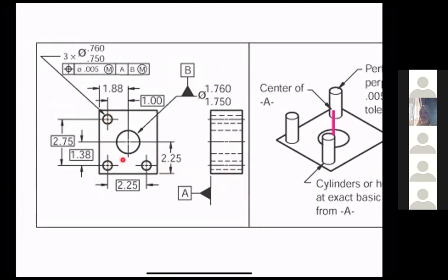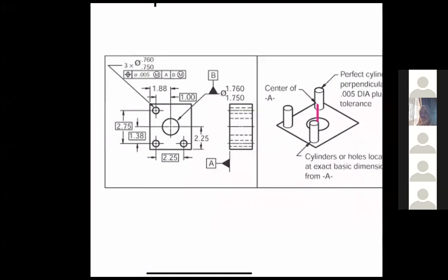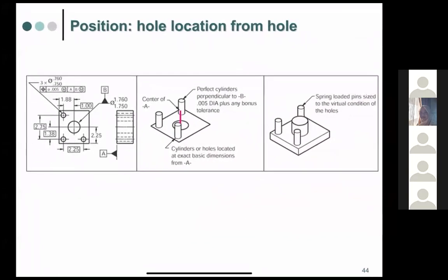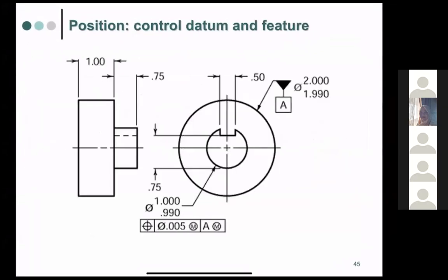Here the position, we write this as the center point, and the center point would be okay as long as the tolerance is just 0.05. Okay, so for example, we want to check the position location from the hole from the center point over there. Okay, this one, so